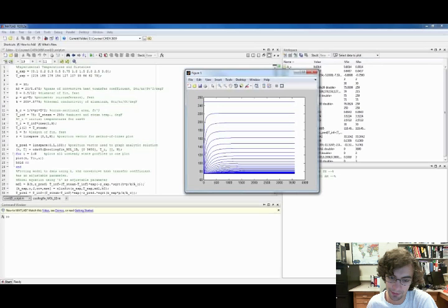And there will certainly be discrepancies between this and the experimental case. You should be thinking about what some of those are. The most obvious, I would think, is that as I have it here, this is essentially a step response. You're saying at time 0 you're allowing heat conduction to occur through the fin. It's not nearly that neat or that precise in the experimental fin setup.